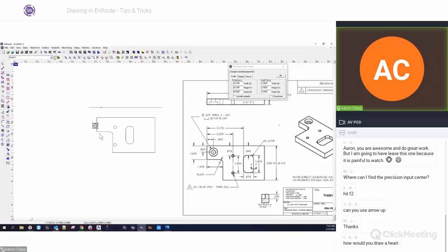I'll also say another thing is when you're drawing stuff by freehand, it's always good to know that you can use your snap tools in conjunction with the other tools like extend and trim lines, for example. So if I need to draw something up and I need to extend a line so that they intersect, I can use my snaps in conjunction with the extend contours. So if I need to extend a contour, say for example, let's grab a good one here.